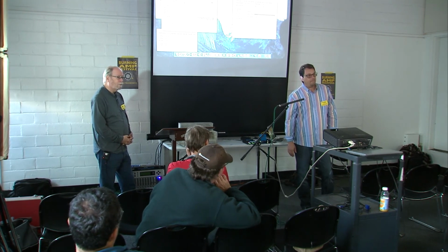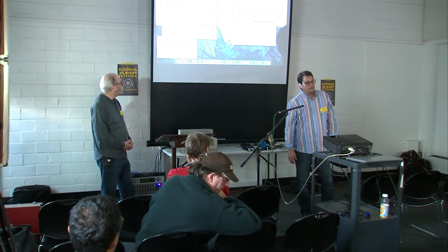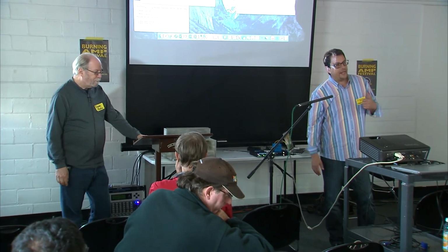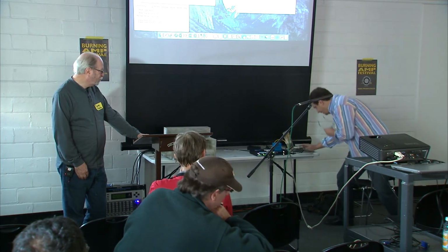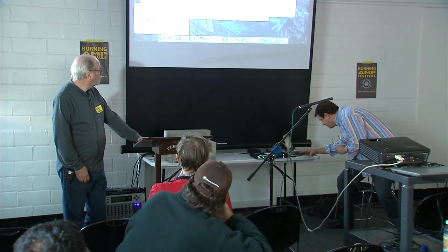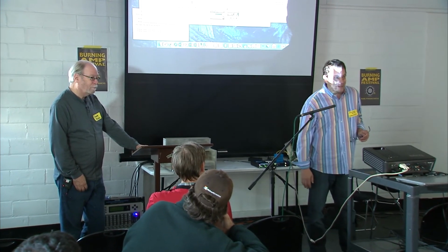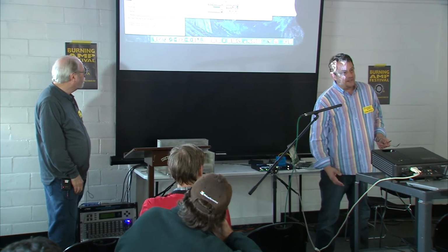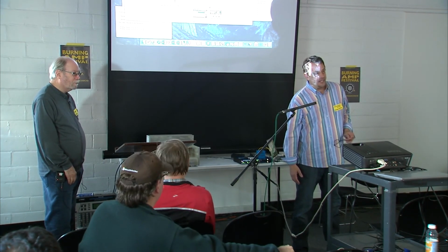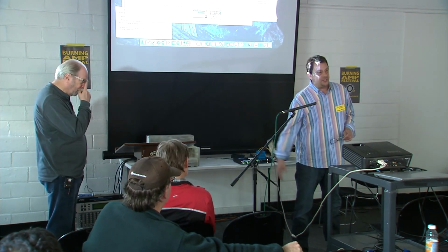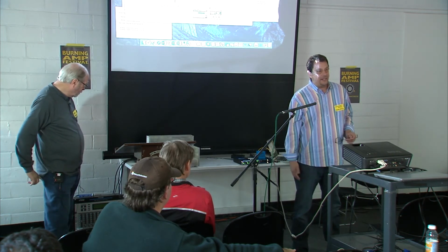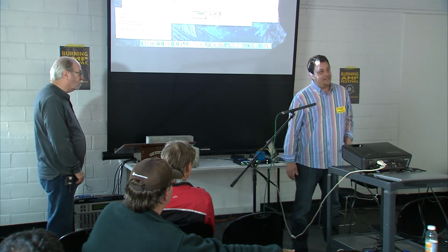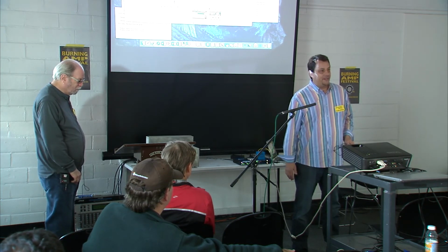Yeah. I mean, if you're measuring an amplifier that has extremely low distortion, you're probably going to need to notch out the fundamental. So, you know, when you get into the high end, I think there's a slide on that. If we go back to the slides. Yeah. 3K is high end. When I was at AP, I saw a lot of stuff for $45,000. But yeah, their 555, which is their best unit, actually does do some stuff with an analog front end, and they have dual notch filters, one for each channel, and that's how they're getting -120 typical across the band and stuff like that. So there is a compromise there, absolutely, but these days the converters are pretty good.